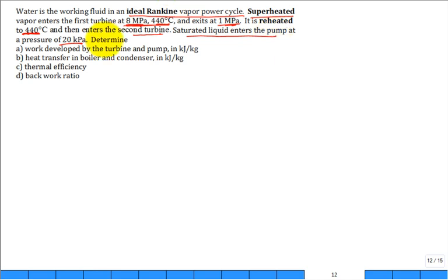So when you're new to a problem like this, a word problem, what is my recommendation? Get a schematic with all your components, and make sure that you don't forget to have 2 turbine stages and going back for the reheat. Then, once you have a schematic illustration, label the states, the unique states, then get a property diagram. So: schematic, states, property diagram, a temperature-entropy property diagram, and then actually put the states on the diagram. Now you're way ahead of the game. If you can do those things, you've got this pretty well licked.